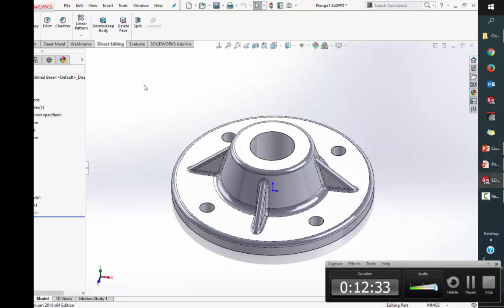Now, if I had a flange that had a straight boss coming out of it as opposed to an angled boss, that might actually be another completely different family. It might have similar features, might have 4 holes, might be the same size, but that one change might be enough for me to look in a different direction. If anything, what I've seen out there with uses of configurations is that people sometimes try to use it a little bit too much. They try to put too many things together in a single part file.